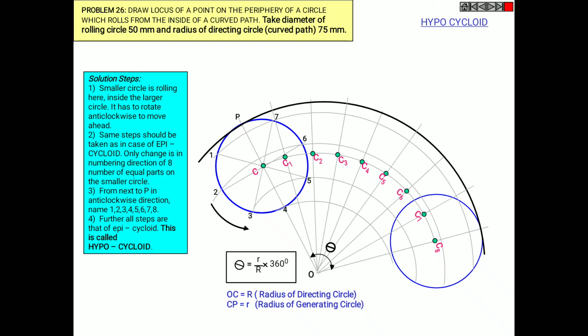See that it is in the anti-clockwise order. Take C2P as the radius on your compass. With C1 cut the arc on the one line, C2 on the two. So mark all these intersections and extend the line with a smooth curve.